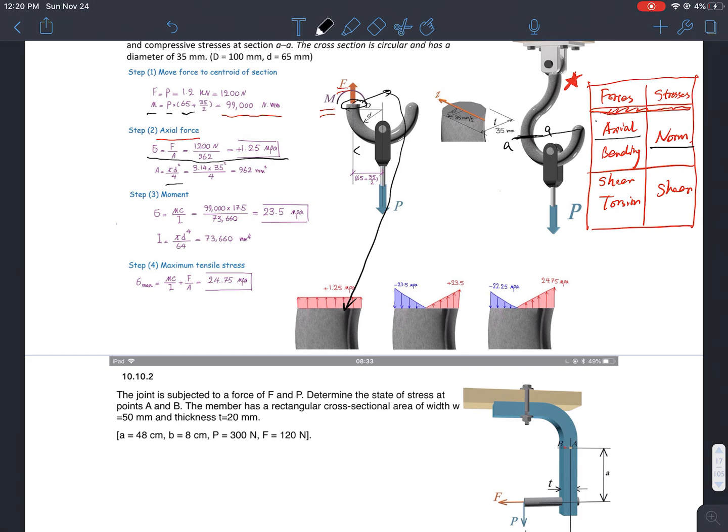Second thing I want to take a look at is if I have any bending moment. I, of course, have a bending moment, which is equal to F times the distance. The bending moment here is determined here, by the way, and can generate bending stress, or normal stress, in terms of Mc divided by I, where c is the distance. So how to pick the distance?